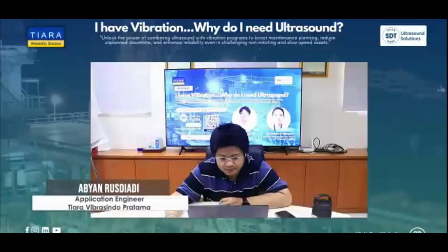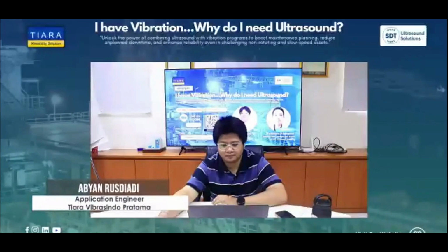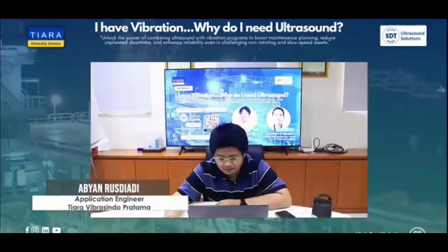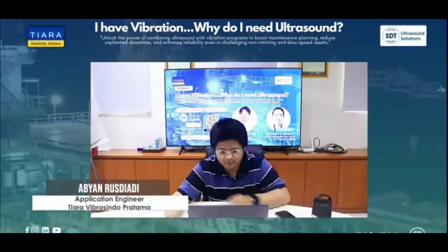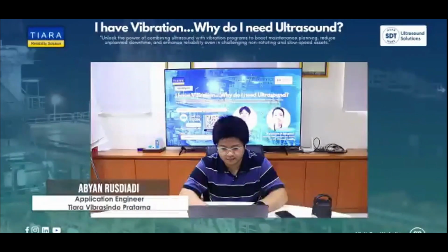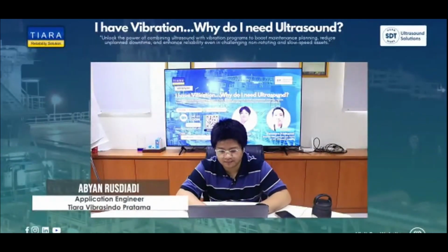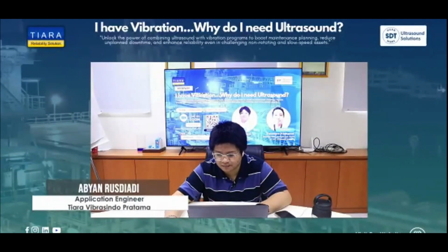Okay, the best approach for the data accuracy, I understand that when you want to measure an electrical problem, for example partial discharge in the power plant, you have noise in the environment, not just the audible sound but the ultrasound also. Almost every ultrasound detector, you can vary the frequency. For example, the acoustic camera also. When you want to measure something, or you use an airborne ultrasound detector sensor to scan, you can vary the range of the frequency.